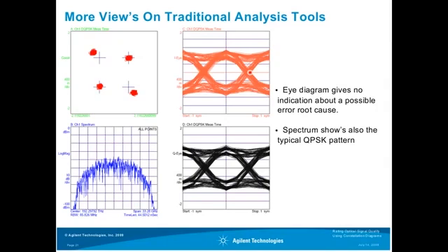And here I have shown you the corresponding constellation diagram that can be seen if you use a DFB laser as a transmitter. If you look at the constellation diagram, you can get the first indication that phase error might be the cause of this distortion. You might be aware that in the constellation diagram, this direction represents the phase, whereas the distance to the origin represents the amplitude. And here we can clearly see that there is phase noise present in the transmitted signal.